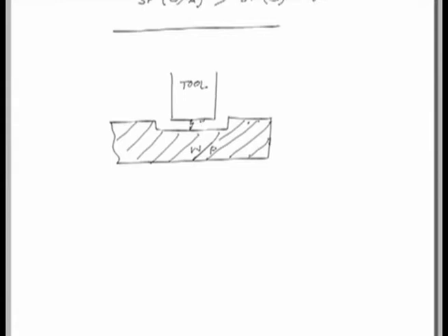Now, because of this sparking, not only will the work material get eroded from this portion and go as debris in this process, but this spark at the same time will cause some erosion on this tool face as well.